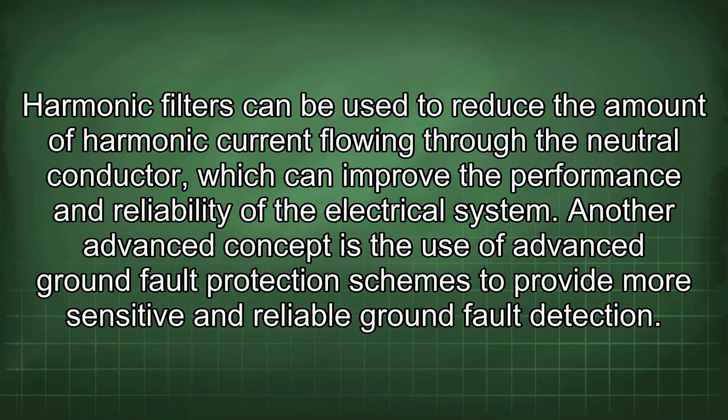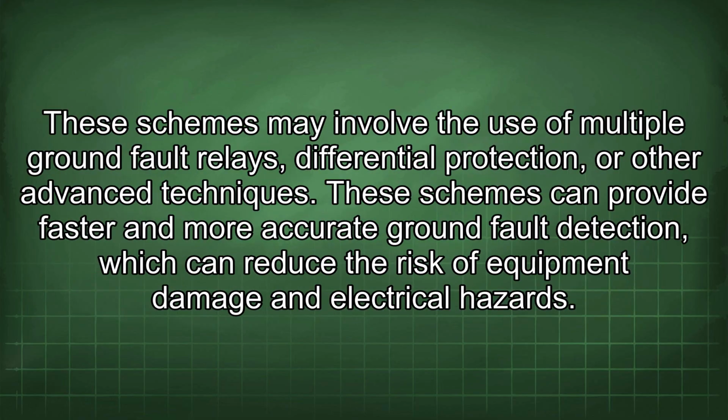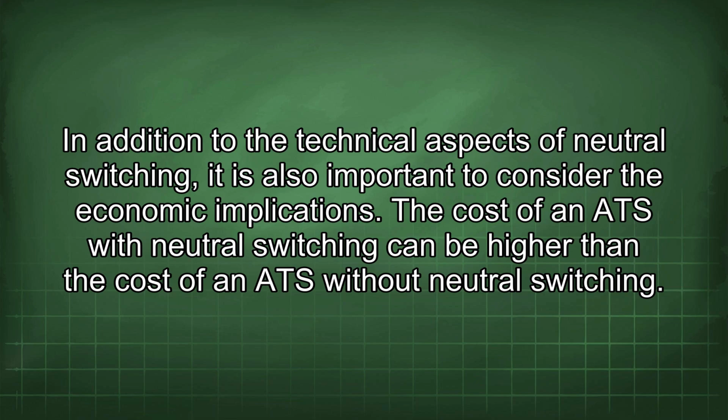Another advanced concept is the use of advanced ground fault protection schemes to provide more sensitive and reliable ground fault detection. These schemes may involve the use of multiple ground fault relays, differential protection, or other advanced techniques. These schemes can provide faster and more accurate ground fault detection, which can reduce the risk of equipment damage and electrical hazards.